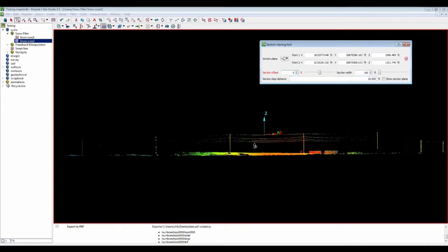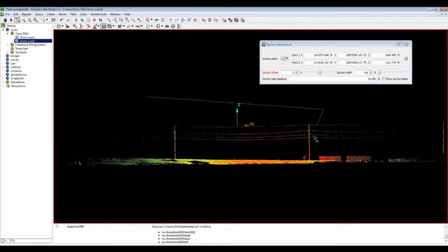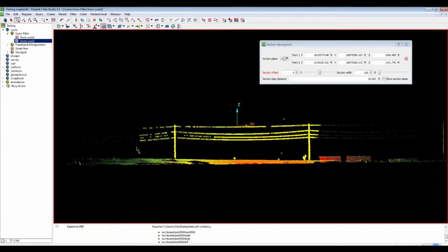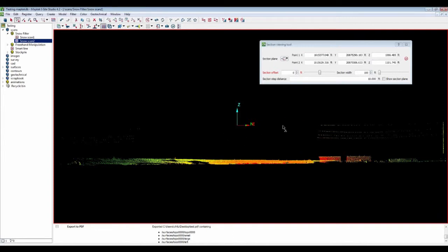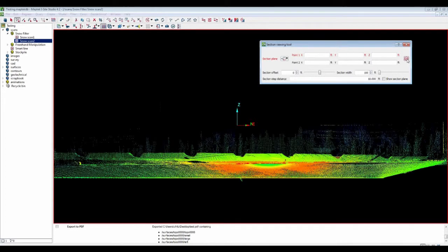So this gives us the ability to come in here, and then we can select really simply using the Polygon select option. We can select what we're not interested in and delete it, and now we're not worried about accidentally selecting points that are in the foreground or the background that we want to keep before creating our model. And this can really easily, just by hitting this red clear button to the right-hand side of the toolbar, bring all of the data back into view, and then it gives us the option to select a different orientation to view it in a section again.